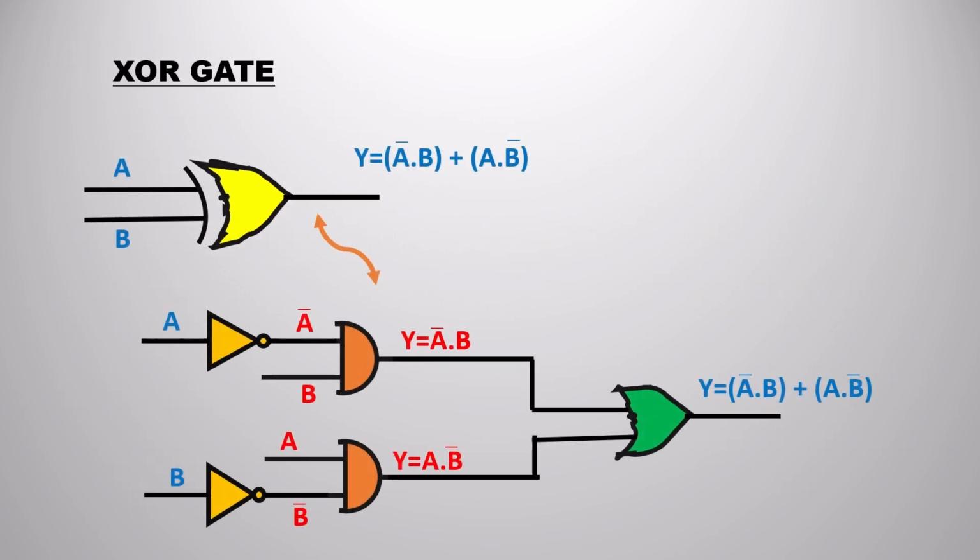So this is the basic circuit, the kind of circuits we are going to see in upcoming videos. With the help of logic gates, we are going to build complex and big circuits like this, and with those circuits we are going to build some output logic. As you can see, the inputs are A and B, so the output we are getting is A bar dot B plus A B bar.